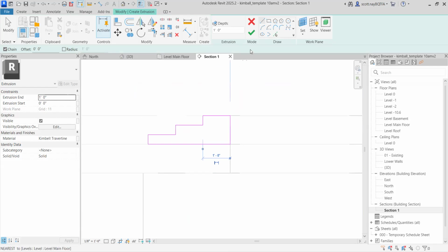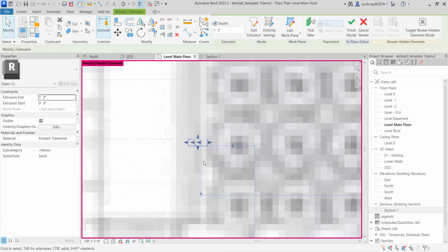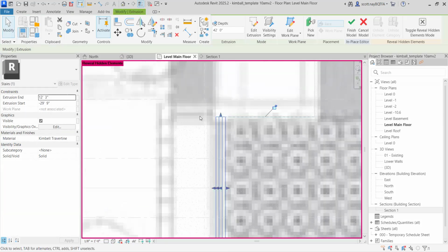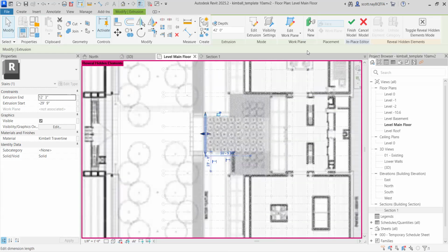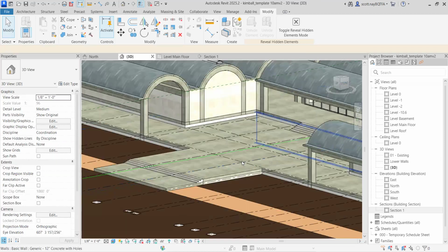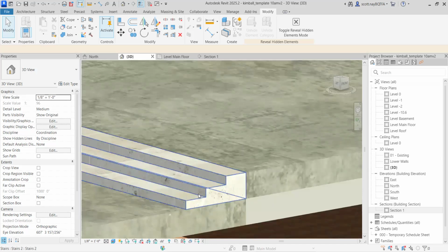Should still be travertine. I am probably going to copy this one. So I'm going to go ahead and disassociate it from the work plane. I'm going to go to my top view. And I'm going to drag this handlebar until I get full width of what I'm making. All right. Cool. That's done. Come back to 3D. Now I have 2 sets of stairs. Everything else I'm doing is the same rise, same run, 3 treads.